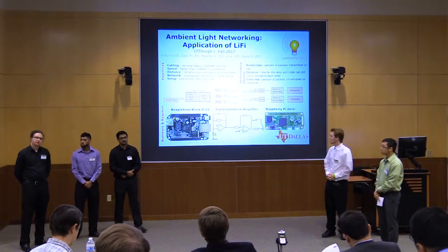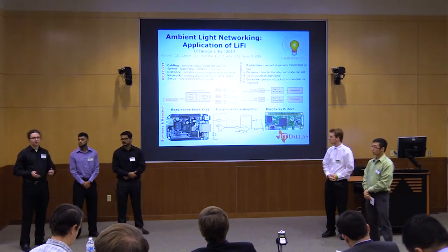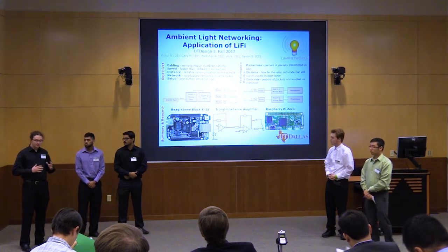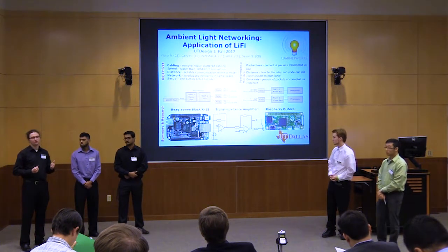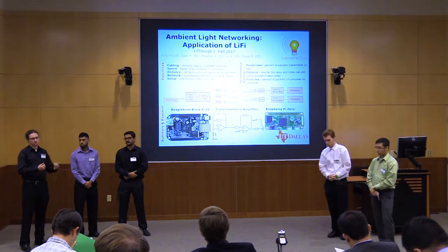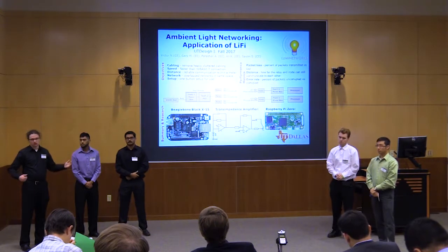What are the considerations when you design the transimpedance amplifier? Ali, would you like to answer that? Well, we need to have it where, in combination with the photodiode, it is sensitive enough and has enough gain to actually get a usable signal across 1 meter.